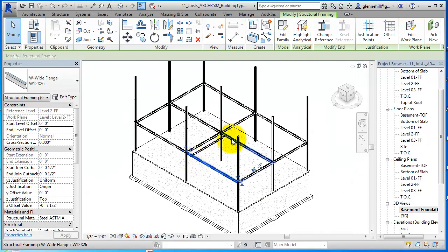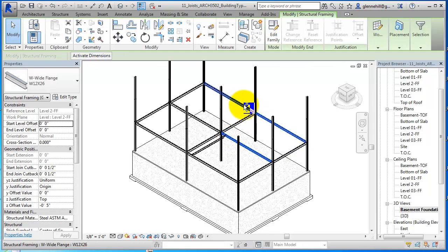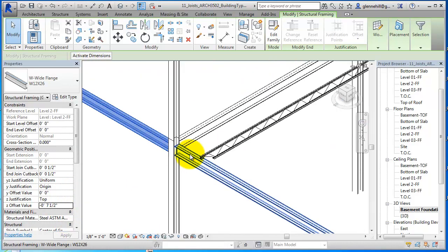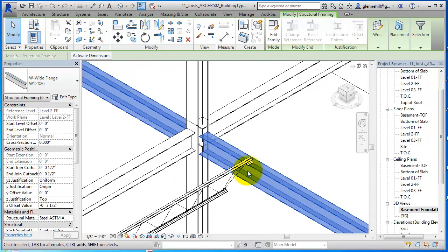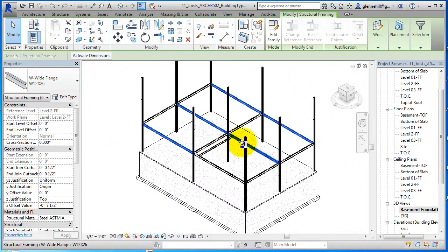And what we want to do is move the other girders. So I'm going to select this girder, this girder, this girder, this girder, and this girder. And we are going to set that to 7.5 as a group. And so we're going to apply that. Boom. Now all of those should have dropped down. So if we look over here, now it's sitting on top. And so we're ready to rock and roll, right?